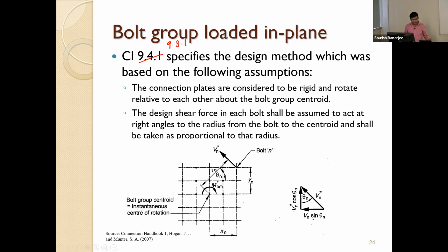In the new standard, some of the clause numbers have been changed. So it is clause 3.9.1, which talks about bolt groups subjected to in-plane loading. Now, look at this figure. In this case, you can see that all the bolts are subjected to the forces or moment in this plane. That's why it is called loaded in plane.